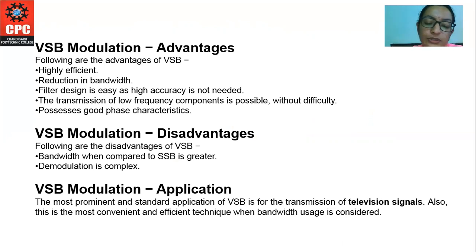The constraint on the filters is relaxed. Therefore, it is easy to design the filters that can be used in VSB. VSB possesses very good phase characteristics, which makes the transmission of low frequency components possible.